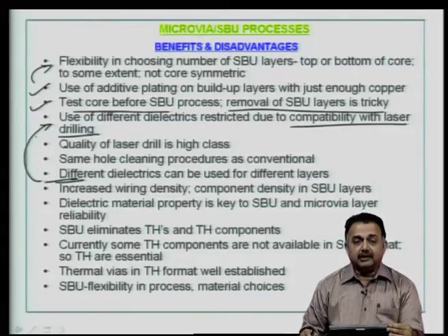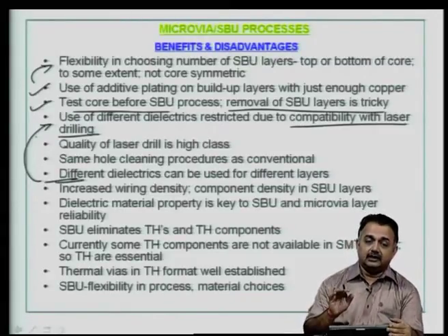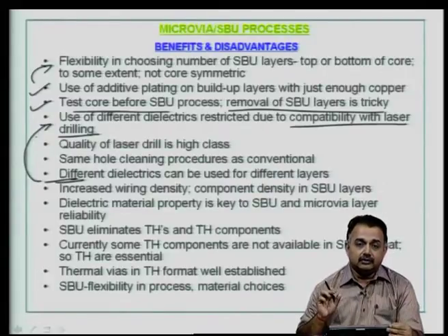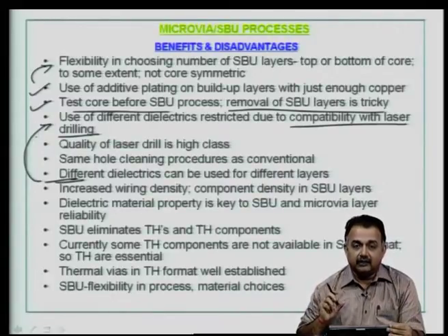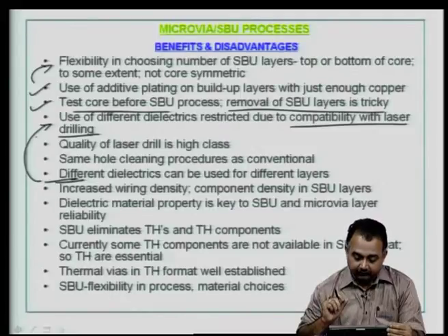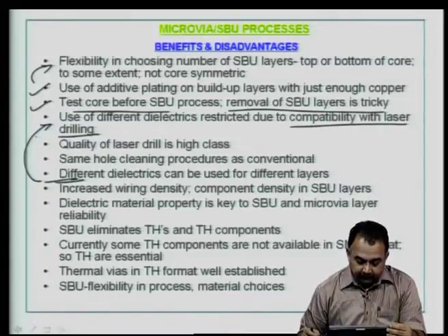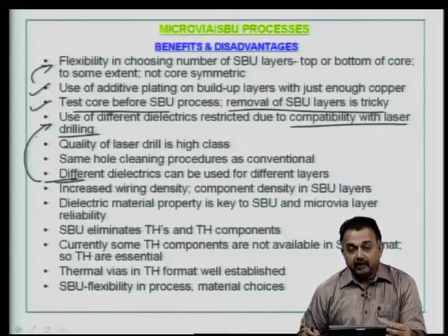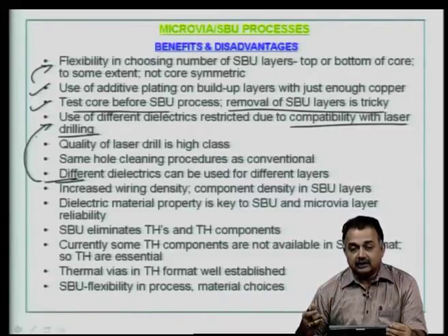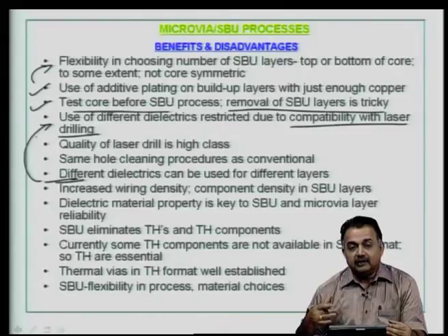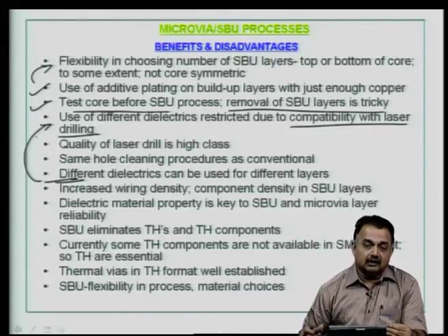The dielectric material that we use for the inner layers is the key issue to providing the kind of electrical properties that you require, and that makes this particular SBU process unique compared to the conventional board. And its behavior during thermal cycling, testing and all that will give us an idea about the microvia and the conductor reliability.